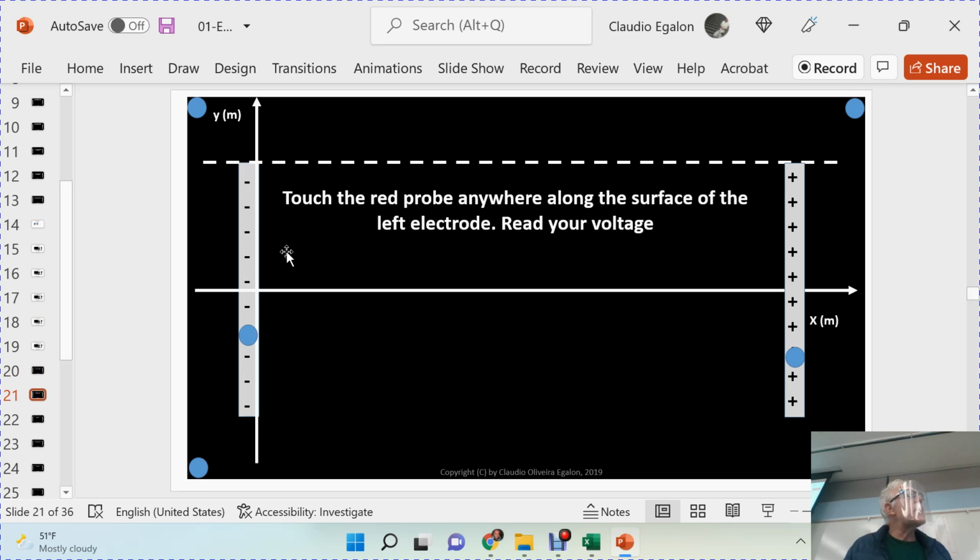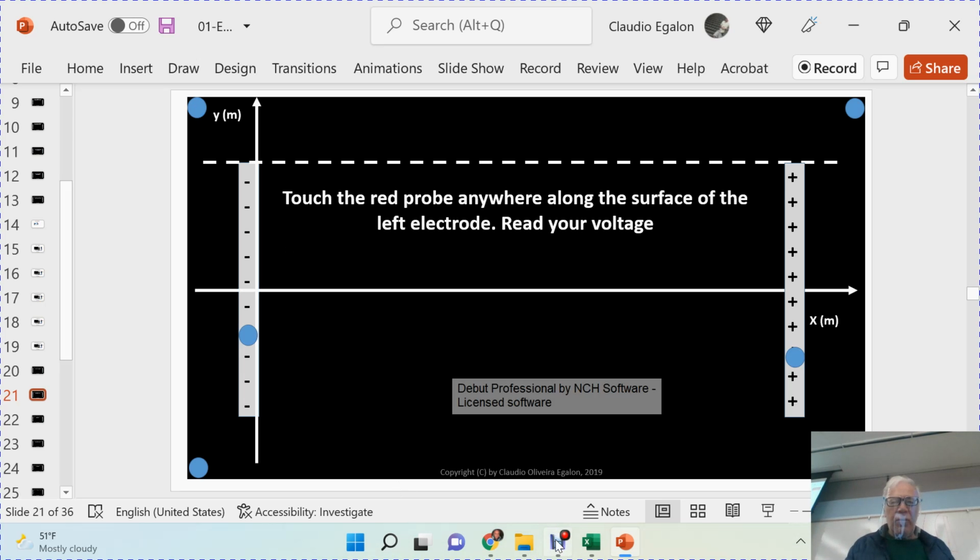Okay. Is that close to 0? Make sure that you don't have millivolts there in the scale. Sometimes you get millivolts there on the right side. You might get like 3 as a number, and then the scale is at millivolts. Do you see that?